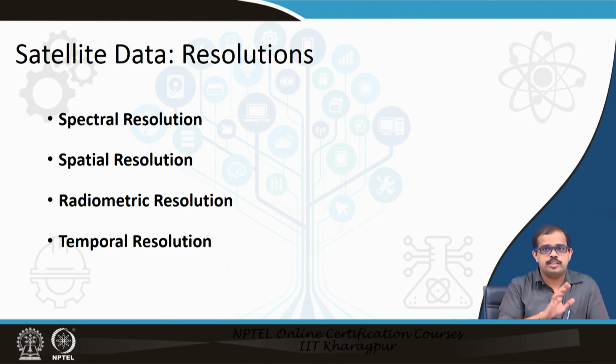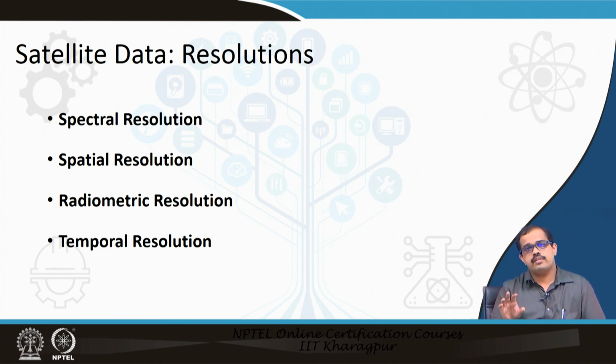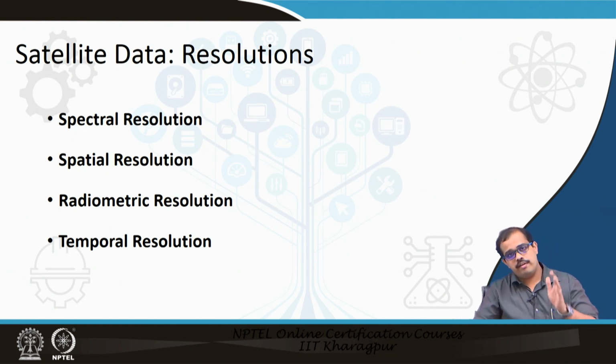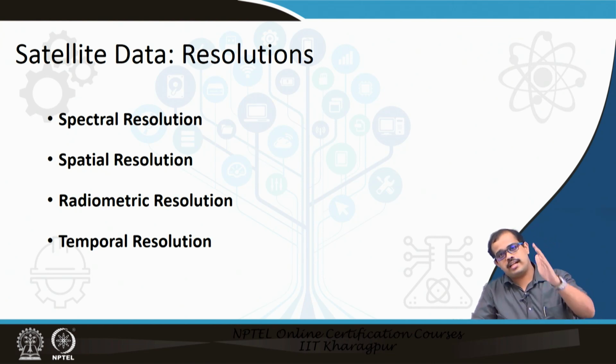The very important aspect that you have to understand is the spectral reflectance curve. If you have understood that, the very basics of remote sensing is understood by you. Okay. If someone has access to a spectroradiometer, please look at how you can measure different plants, different soil. So, you will understand how this particular spectral reflectance curve versus wavelength is actually computed. Once we have understood that, let us go to the satellite.